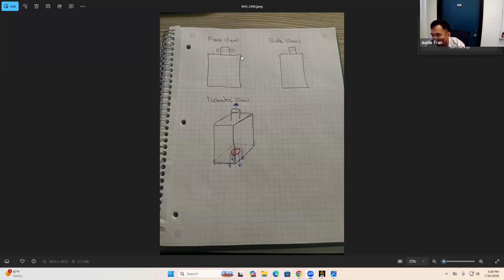I think that would be good. Let's see what else. So that would be one load, and the load experienced at the bottom could be a second one. We're looking for two different loading scenarios, so different ways to configure the boundary conditions. One would be the tensile load, and one way to do the tensile load would be based on the acceleration that we just computed.